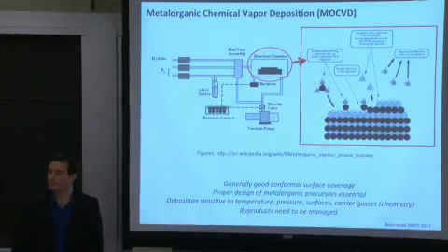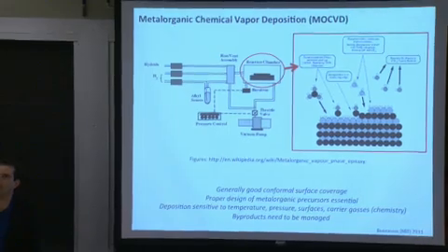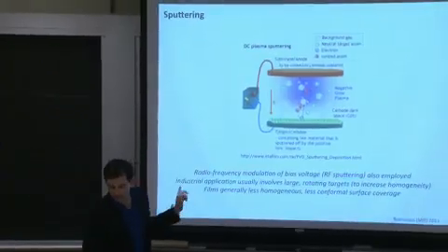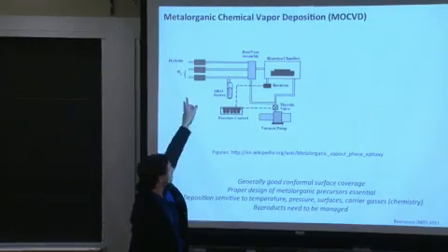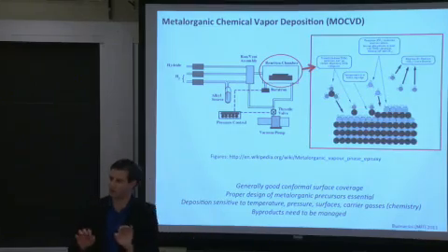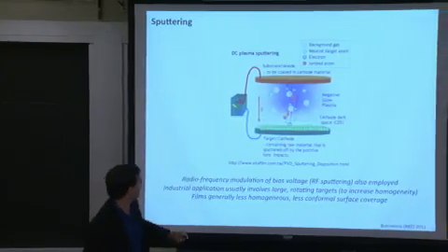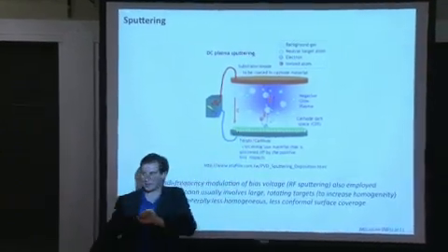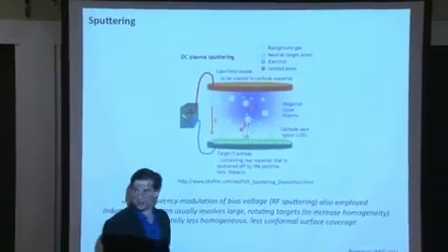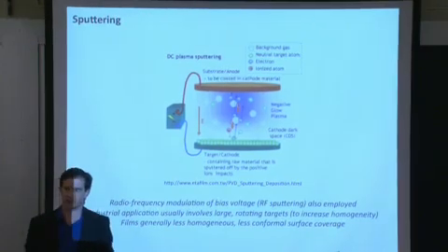Yes? And the purity quality is much better for MOCVD than it is for sputtering, right? It depends on a lot of factors. So the reason the purity of MOCVD is generally better than sputtering is because the mass flow controllers necessary to control the gas flow are specific for particular types of gases. Now in sputtering, because of the versatility of the sputtering chamber, you could take this target out and put in another target, maybe Ashley comes along into your sputtering chamber and puts in a target of another metal. And now you're depositing 2 different metals in the same sputtering chamber, you're going to get cross-contamination.